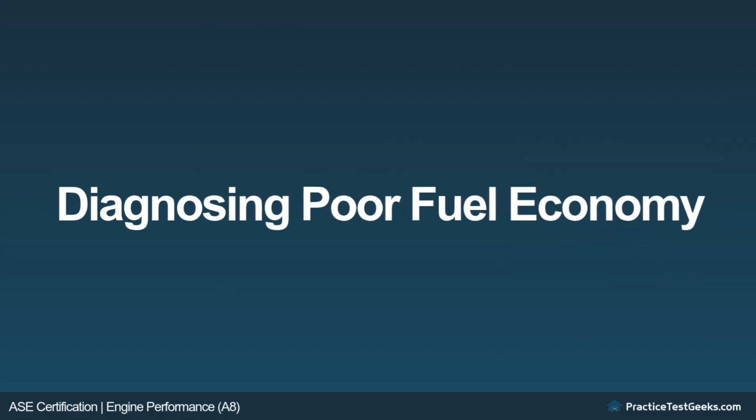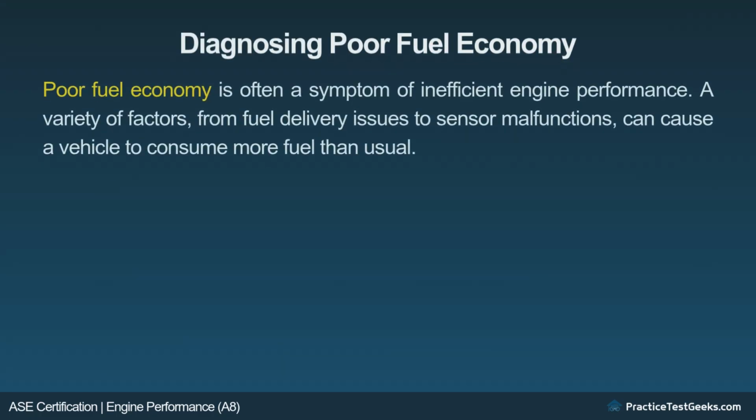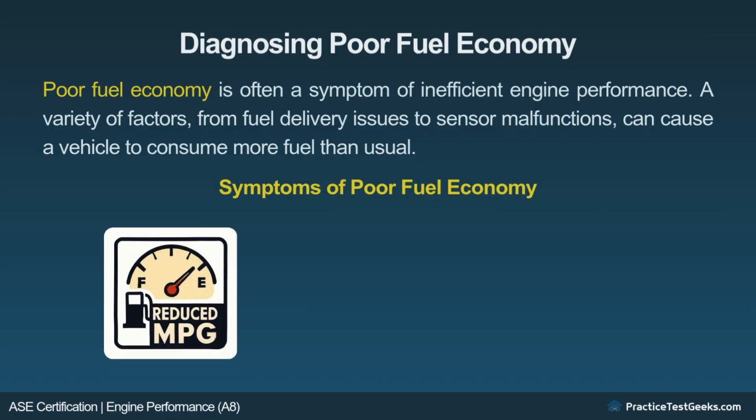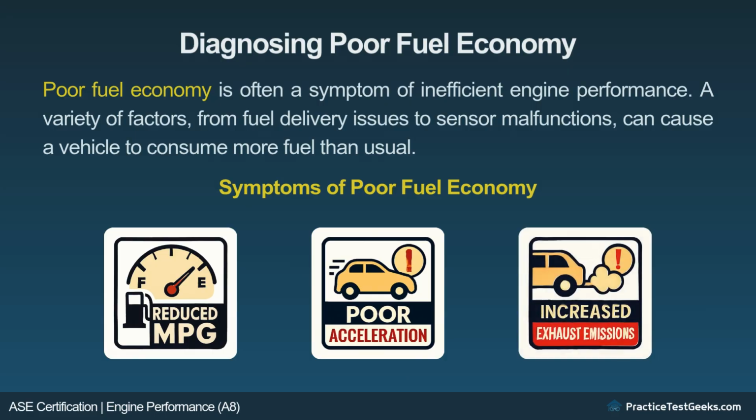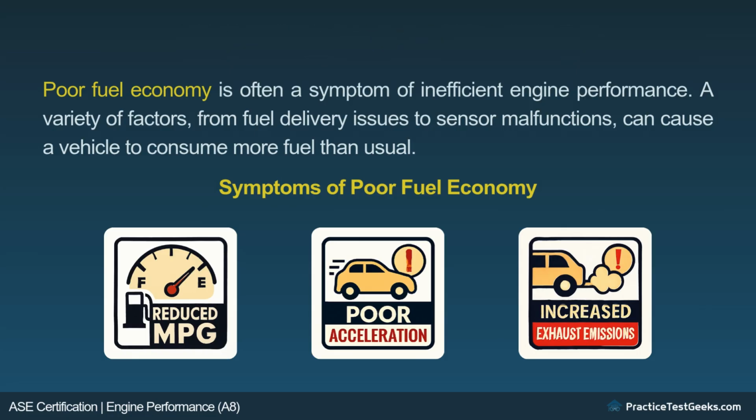Diagnosing poor fuel economy. Poor fuel economy is often a symptom of inefficient engine performance. A variety of factors, from fuel delivery issues to sensor malfunctions, can cause a vehicle to consume more fuel than usual. Symptoms of poor fuel economy. Reduced miles per gallon. The vehicle requires more fuel to travel the same distance. Poor acceleration. Reduced throttle response may indicate the engine is not operating efficiently. Increased exhaust emissions. Excess fuel that does not combust properly leads to higher exhaust emissions.